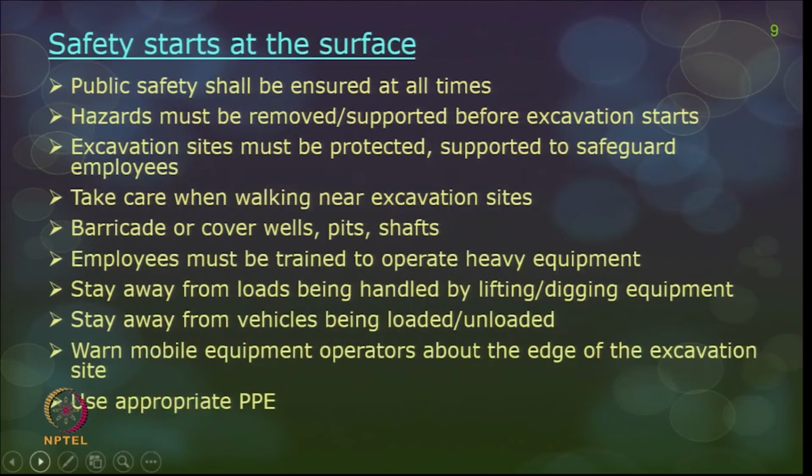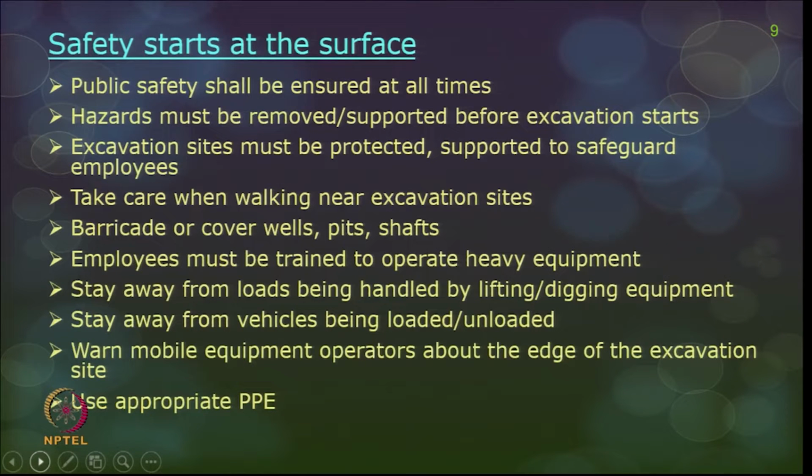The existing structures, if available, should be safeguarded properly, and only then should you start with your excavation. So, many of the safety precautions start even before you start your excavation. Number 1, public safety should be ensured, which you have seen earlier.